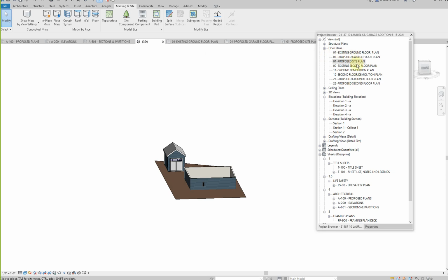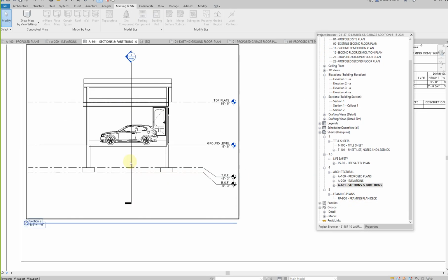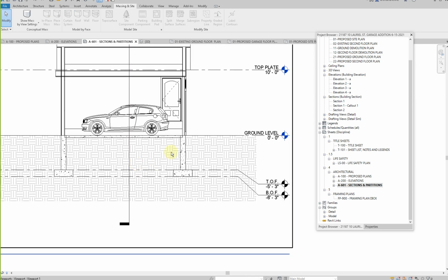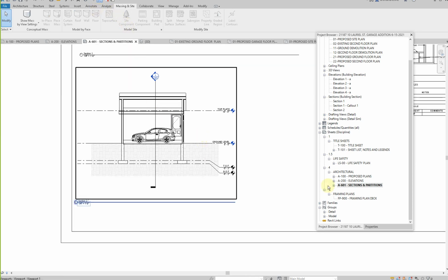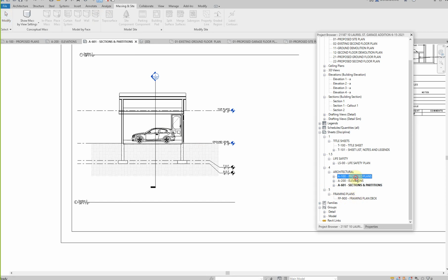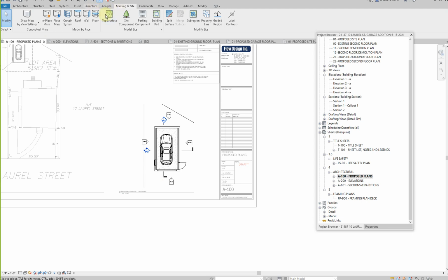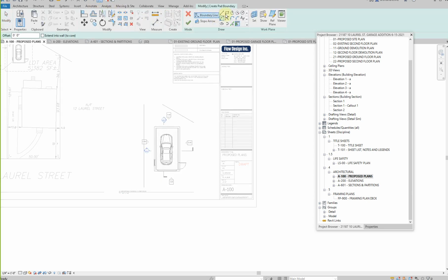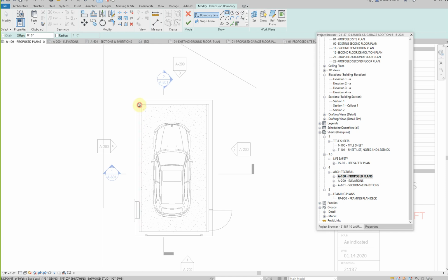We got a problem now, which you wouldn't see yet, but you're gonna see it in the section. We have the dirt going right through, so we need to do something called a building pad. You would do that on floor plan, and then on your floor plan, you're gonna come here and say building pad, and just draw a rectangle all around the inside of your space.